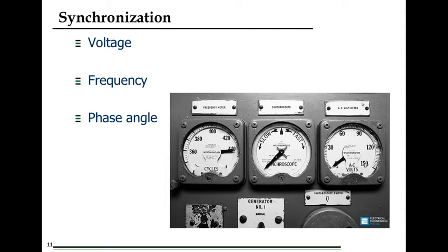Second parameter which we are talking about is voltage. So when we have switched on our excitation system, we get generator terminal voltage. Suppose our generator terminal voltage is 25 kV. Now generator is connected to generating transformer, and this generating transformer is then, after some electrical equipment like CT and PT, connected to grid via circuit breaker. So while synchronizing that, we give a closing command to this circuit breaker. Suppose we are synchronizing our generator to a 400 kV grid. We have a 500 megawatt generator, generating terminal voltage is 25 kV, and generating transformer will step up this voltage to 400 kV.